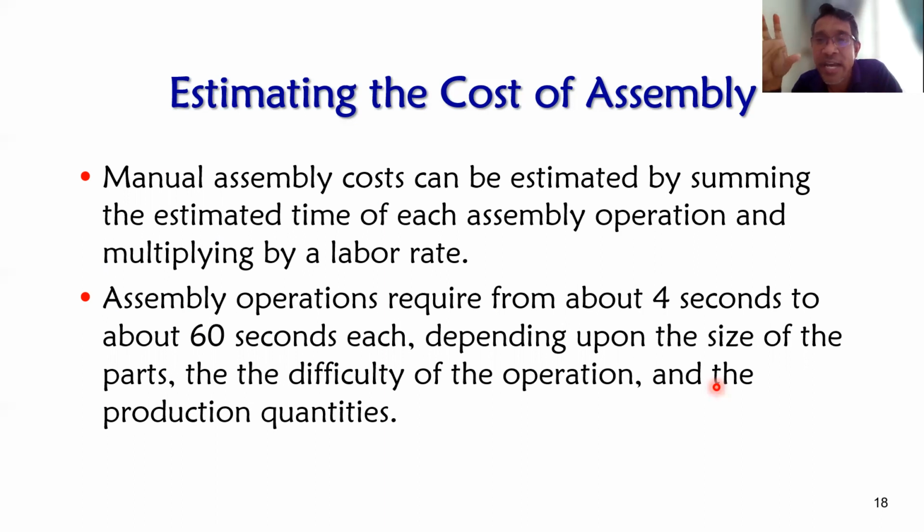The quantity may be small, but they need to use that particular machine. We cannot do soldering one by one for maybe 2 units, but if we have 100,000 units or 1,000 units, we need a specific machine to do it. So even at relatively low volume, we need to consider automatic production for the electronic circuit.